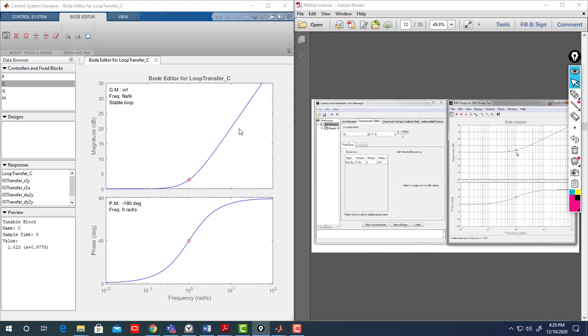And the derivative factor, as you see, amplifies the high frequency. And usually noise in the system is high frequency. That's why derivative in practice amplifies the noise. So if that's my wanted signal, and the noise on the measurement is high frequency, the period is very low, so the frequency is very high. This high frequency signal, when it goes to the derivative, will be amplified, this is the magnitude, remember, and therefore I may lose my signal.